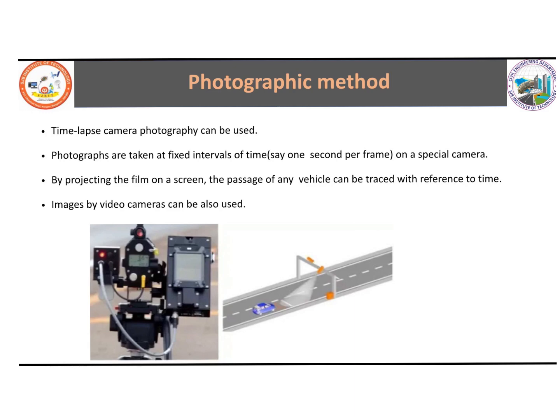When the vehicle is moving, you will know the first reference points. Note down the time required for the vehicle to pass two reference points in the video. You will run the video as a film, and on the screen just note down the passage time of the vehicle. Once again, the distance divided by the time will give you the speed of the vehicle.